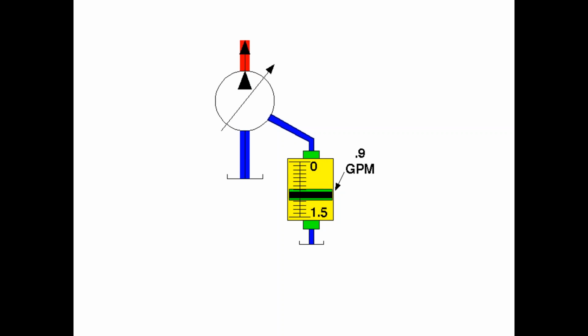It doesn't just happen. The pump's not usually going to be fine today and just wear out tomorrow unless something makes that happen. Most pump wear is going to be a very gradual thing, and if you track it, then you can change that pump during a scheduled outage instead of having to interrupt production.